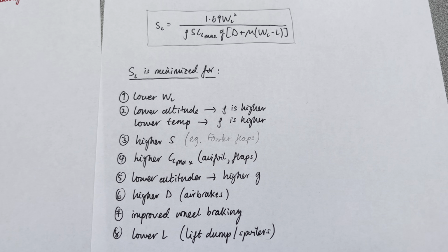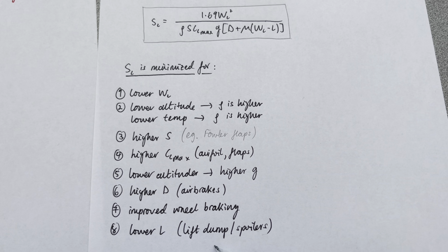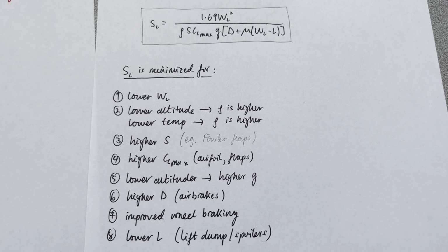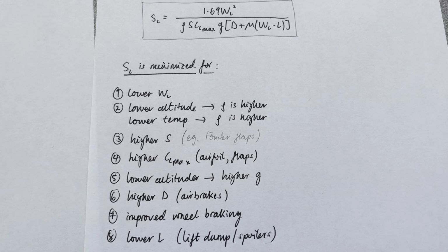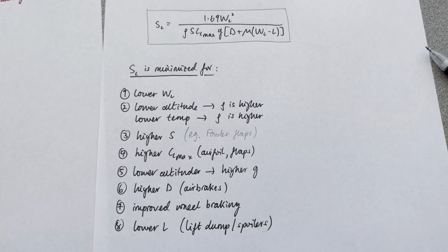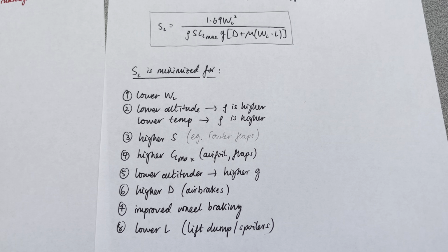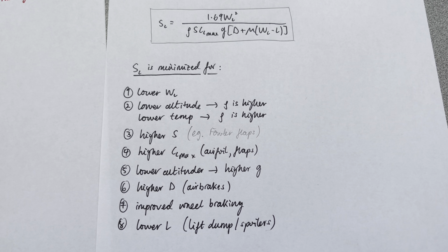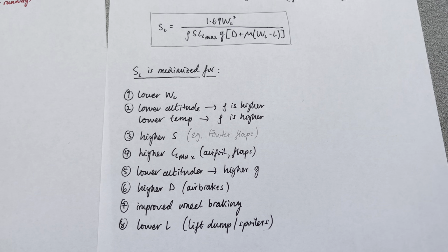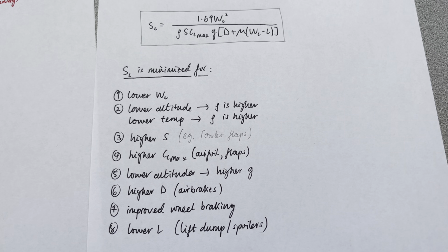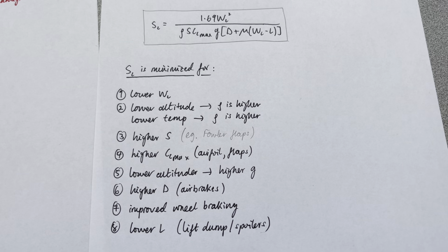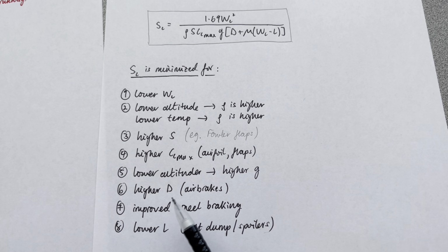You might hear pilots refer to that as lift dump, and essentially they're just little flaps which extend from the upper surface of the trailing edge of the wing and just basically deliberately spoil the lift so that the airplane sticks to the runway and helps us decelerate as quickly as possible. What we don't want is for the wheels to touch the ground on landing and the airplane to start floating along the runway as we're trying to decelerate, because obviously that will negate our wheel braking here.